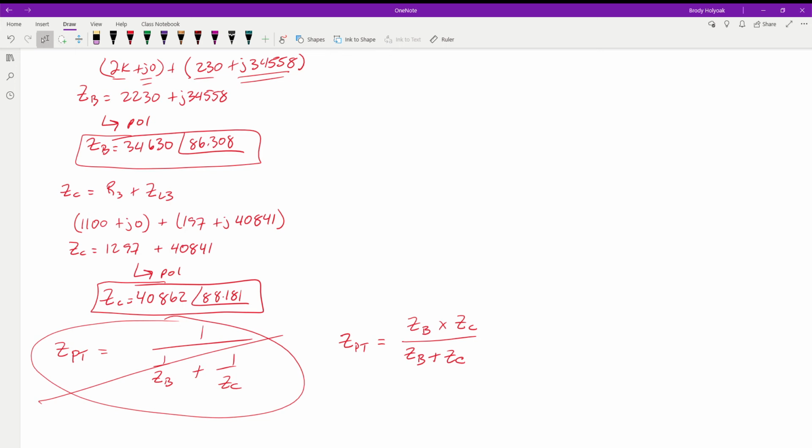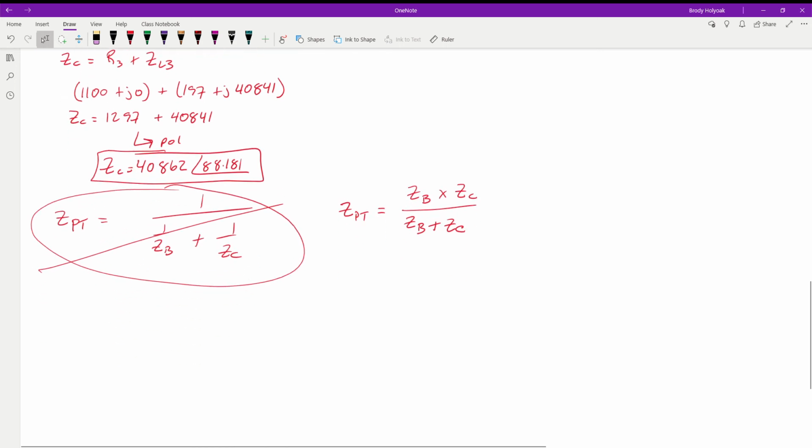And then you just have to remember to subtract that value through, but you'll end up with a final value in rectangular form that you can use. But again, then we're going to be dividing, so they need to be in polar anyway. So it's just kind of a good idea in practice to at least have your impedances in both rectangular and polar form as you go.